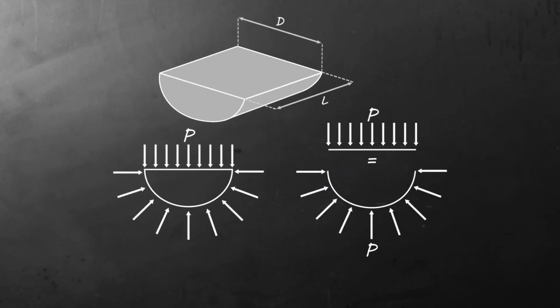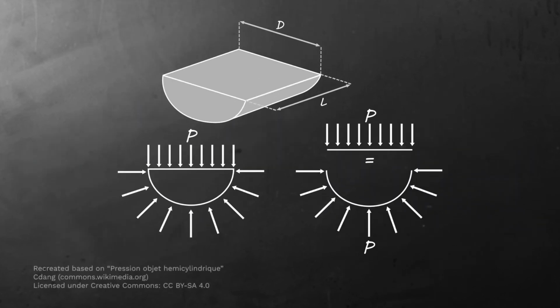Now let's shift gears a little bit and think about what happens if the surface is not flat. As long as we have a flat surface, all of the pressure components are going to be parallel. They're all pushing in the same direction, so we simply multiply the pressure by the cross-sectional area. As long as the pressure is constant, that'll work. But if we have a curved surface, then we're looking at a distribution of directions. And that complicates things a little bit because a pressure is always perpendicular to whatever surface it touches.